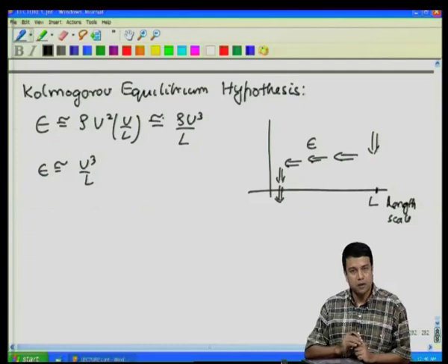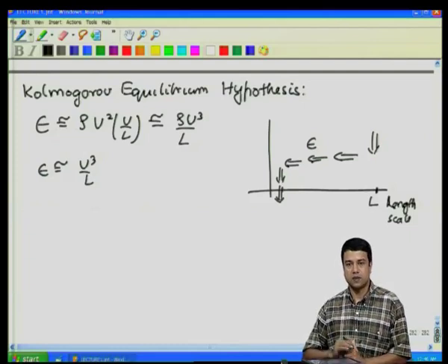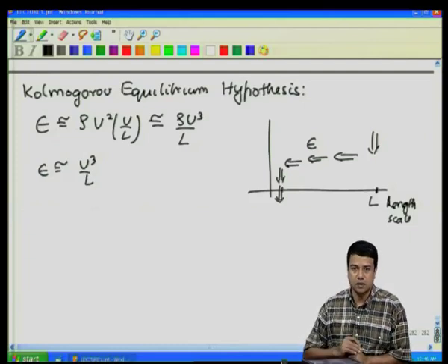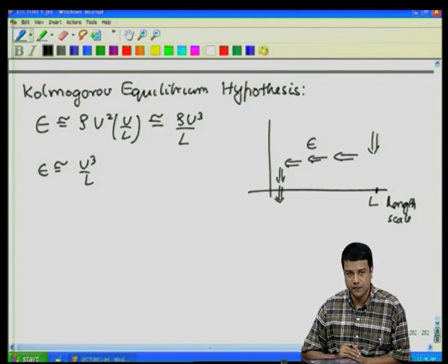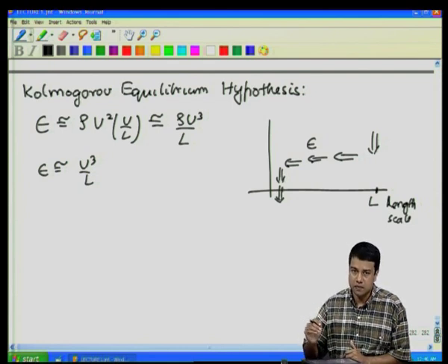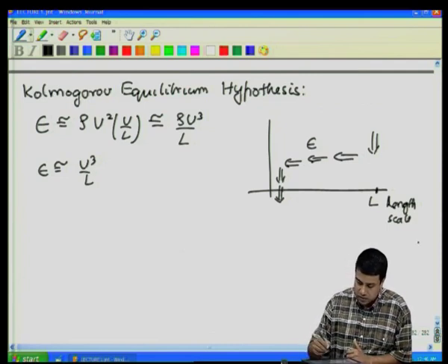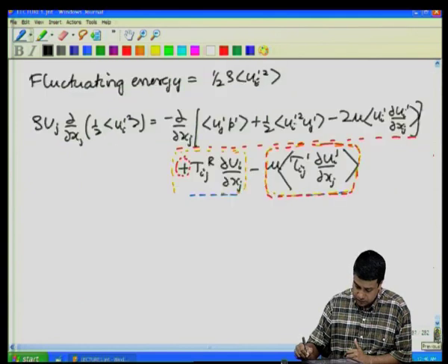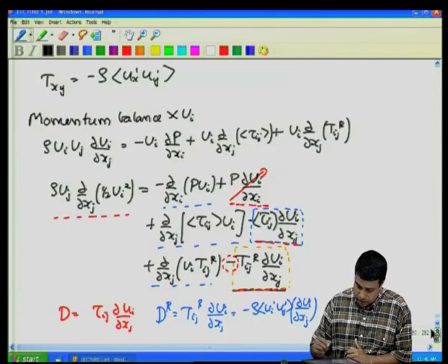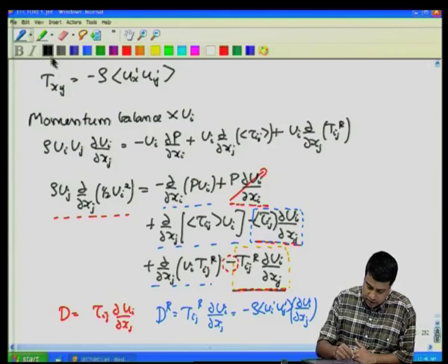Take out the density, because that is the only one that has the mass dimension. We work with dimensions of length and time. So, these are the dimensions for the macroscopic flow with the macroscopic velocity capital U and macroscopic length scale capital L. You would expect the rate of production from the mean flow to be U cubed by L. This also comes out of the fact that for the mean velocity, this gives me, this term is the production term.